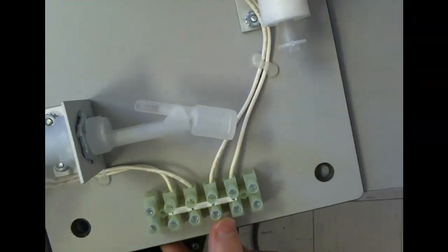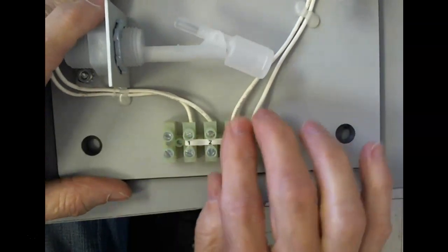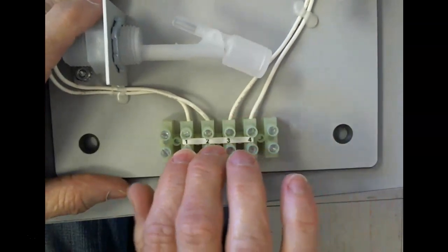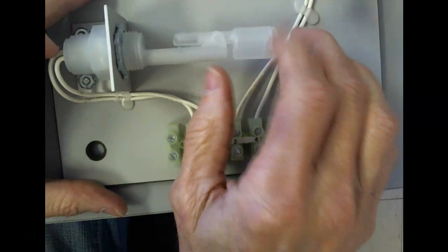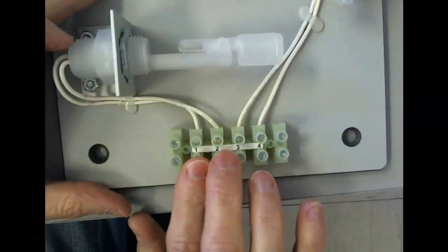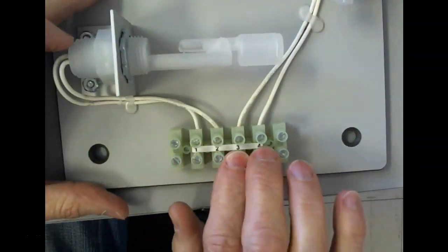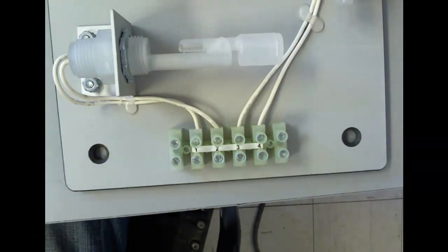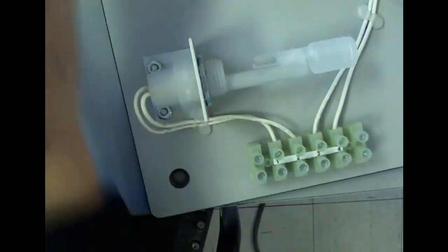So this one you really don't need the wiring diagram because it's pretty obvious which numbers these come down to. One reed switch comes down to 1 and 2, and the other one comes down to 3 and 4. These are going to be digital. Are we okay? Any questions on that one?